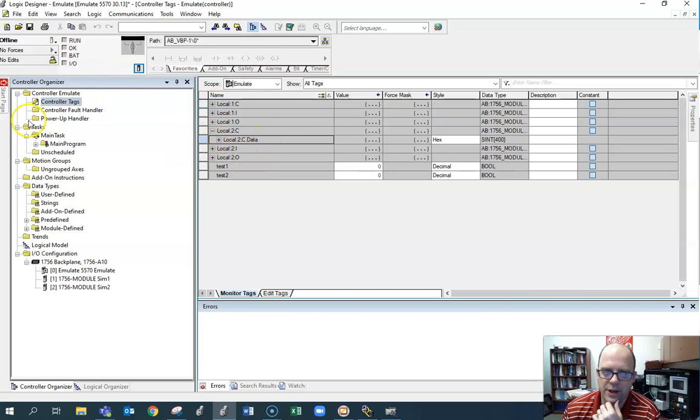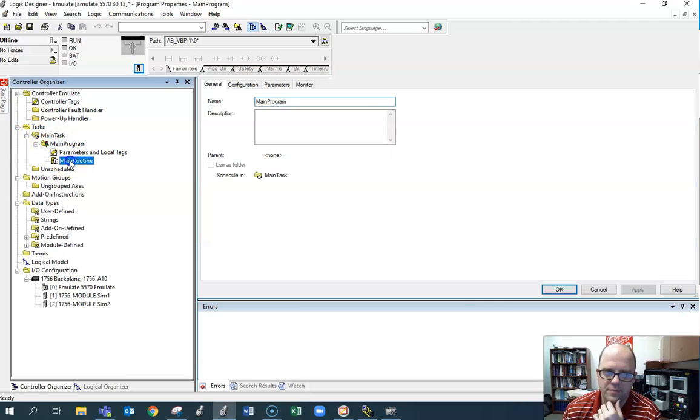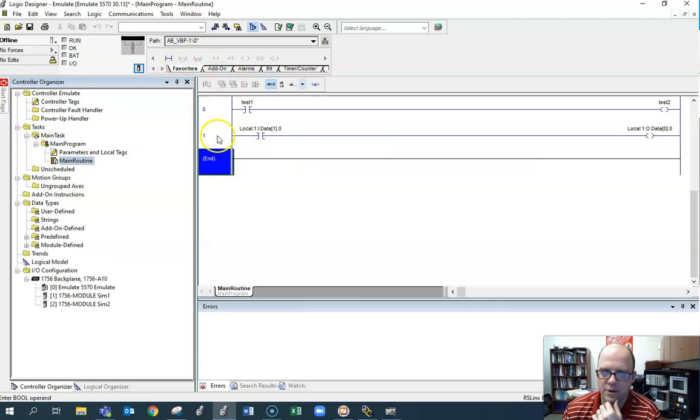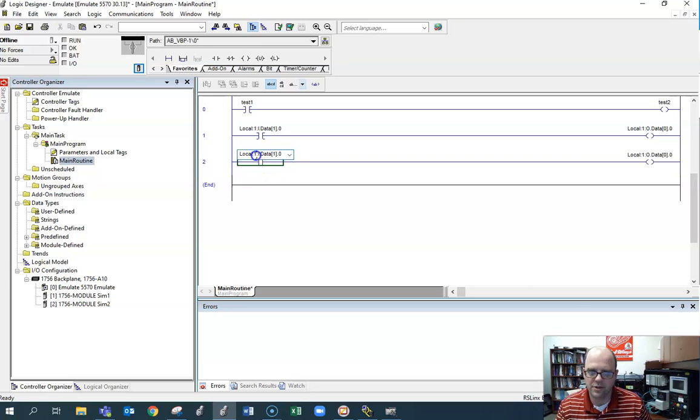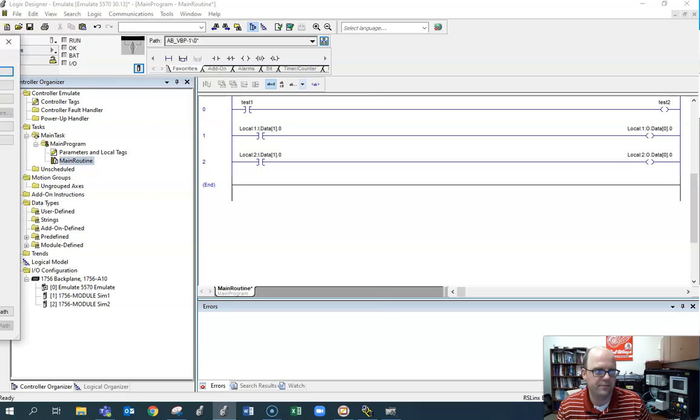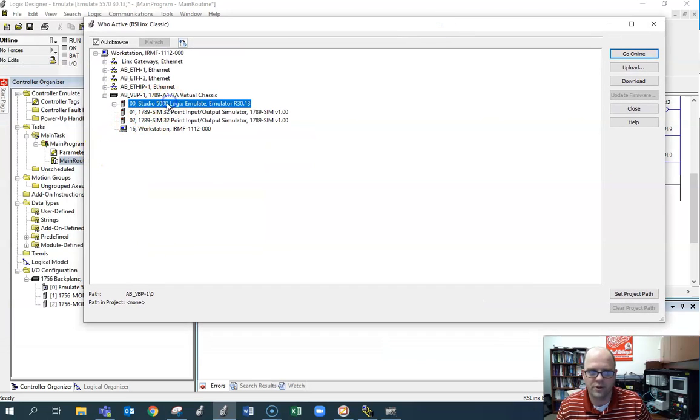But now if we go in and do programming, I can go in and I'm just going to copy this rung, and I'm just going to change this to a 2 and change this to a 2 just to demonstrate. And so now I can download. Well, you got to make sure you set your communication path to your emulate.